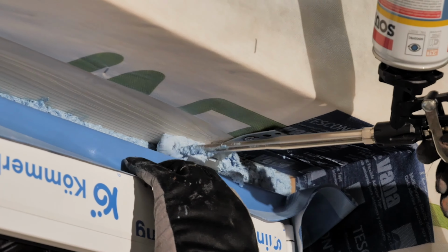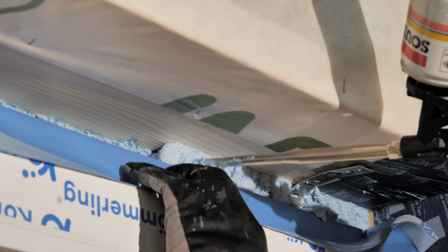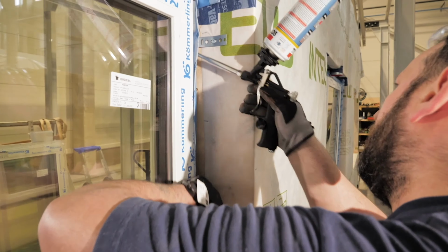Once the window is installed and sealed with foam or mineral wool, perform a quality check of the sealing to ensure it is secure. Next, add window trims as a finishing touch. Be cautious when cutting sheet metal trims, as the material can be very sharp. Finally, add compensation wool to the inner side of the element to ensure maximum efficiency of the element.